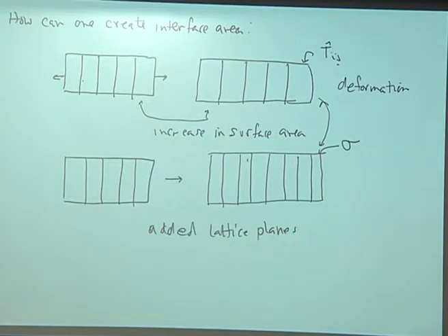Okay, and if you think about this simple little analogy here, now you understand why the chemical engineers mix up surface tension and surface energy all the time. Because think about what if you did the change that I have up here. What happens if I take a fluid and I stretch it like this? What happens is that atoms move from the bulk of the fluid up to the surface. And so you create more area by adding more atoms at the surface, which is basically that variation. So they get mixed up together. So in a fluid, these two things are the same. In a solid, they're not.